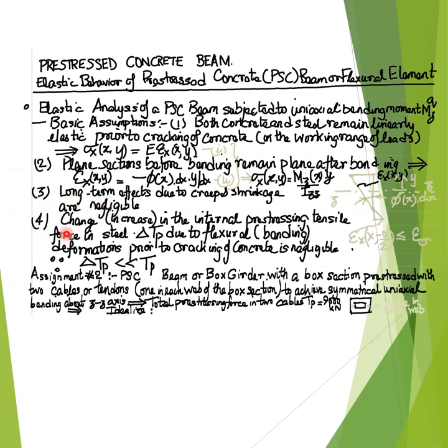And the assumption number 4 implies that the change or the increase in the internal pre-stressing tensile force in the steel in case of the pre-stressed concrete beam, delta Tp, during the flexural or bending deformations, is negligible prior to the cracking of concrete.